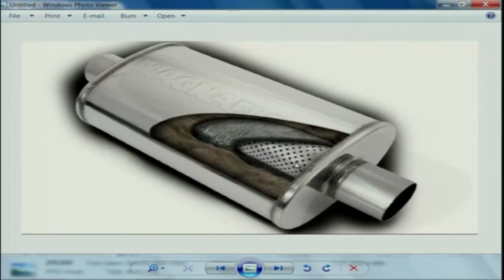You see, this is the part and this connects, of course. Let us say there is the inlet, and this is the outlet where my mouse is pointing. The flow comes in here and is smoothly guided by the perforated pipe and leaves outside. It is not allowed to expand freely. The acoustic waves nevertheless are allowed to interact with the cavity, and the cavity is not empty now. As you can see, it is surrounded by some sort of glass wool and mineral wool. These are nothing but dissipative materials. They completely kill or dissipate the acoustic signal.